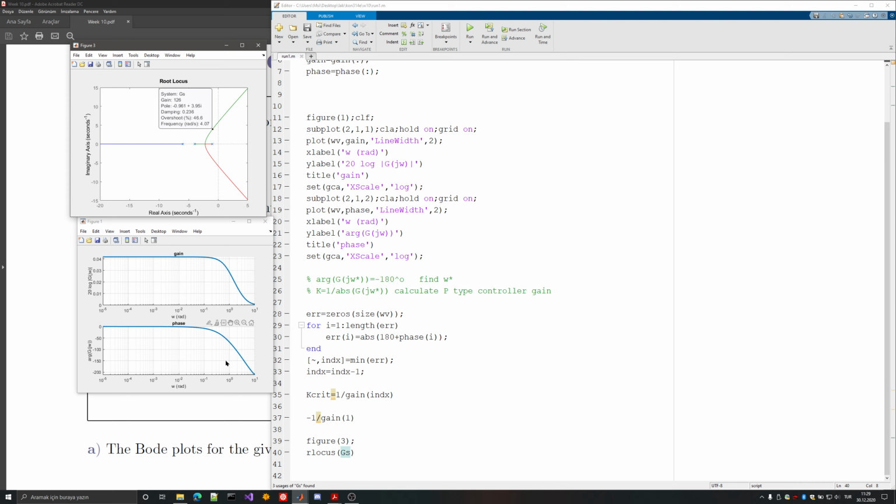So if somewhere around minus 180 degrees I have instability, I should, since you can see from the gain, I'm basically increasing the frequency. So for this plot, I can see that maybe I'm looking for somewhere here. So I need a certain phase angle that corresponds to my behavior, and this phase angle is less than minus 180 degrees, or it's somewhere around here. It can be here, it doesn't matter, but it is somewhere on the left of the critical point.